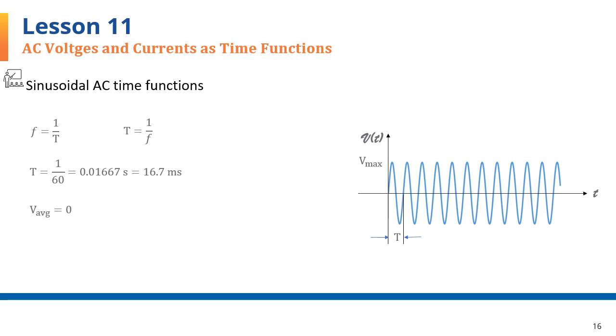In practice, however, in a power system, the maximum Vmax can gradually shift over the 24-hour period of the day, depending on the conditions governing the grid at any time. Also, at the same moment, the voltage can and does have different maximum and effective values at different points of the grid, again depending on the distance from the generation centers and conditions of the grid at the time.